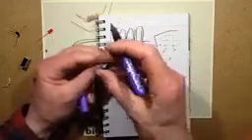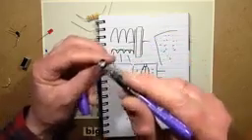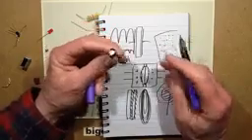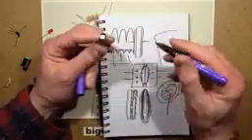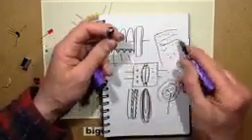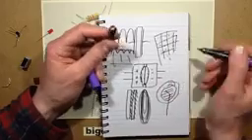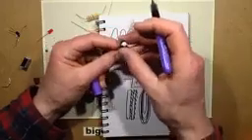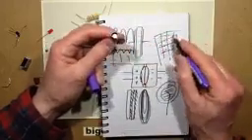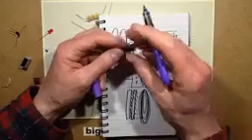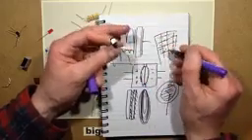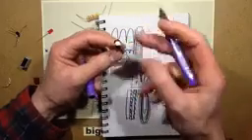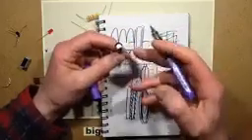They're put under a lot more stress. And if you look at the top of this one, you'll see there's a little cross on it, and that's a safety vent, because when these fail, what actually happens is that oxide coating can be perforated, and that's really common if you accidentally connect them in reverse, because it relies on the polarity to keep that oxide coating intact. When you connect them in reverse, that fails, and then suddenly you've basically got this liquid-filled thing just connected across the power supply with no current limiting it.